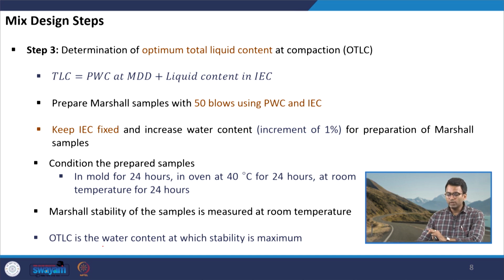Okay. So, how do we determine the optimum liquid content? I will prepare Marshall samples. So, I have to do a Marshall compaction here using 50 blows of compaction on both sides, using the pre-wetting water content and initial emulsion content. Okay.